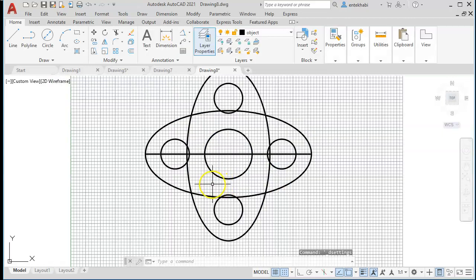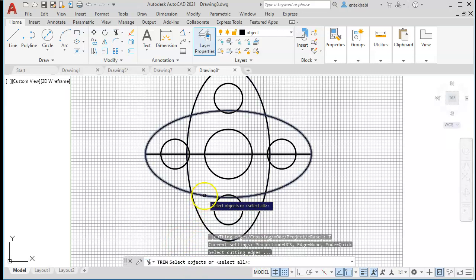that completes almost everything. Besides, I need to do some trimming. My handout sheet maybe is the old-fashioned way, where you have to define the cutting edges, but cutting edges are built in as a default. So when you go to the trim command, the little scissors here, you don't need to define cutting edges, but I'd like to do that by selecting the cutting edges first. Then I pick the two ellipses. This way I don't have to go piece by piece.